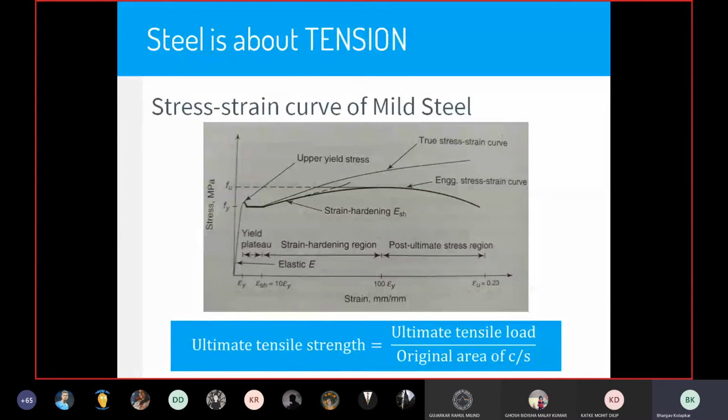As Vidisha rightly said, the amount of resistance that a material offers to an externally applied force is called stress. Mathematically, the first answer that I got, stress is equal to force upon area, is correct. But actually, stress is the resisting force upon area. Do you understand the difference?